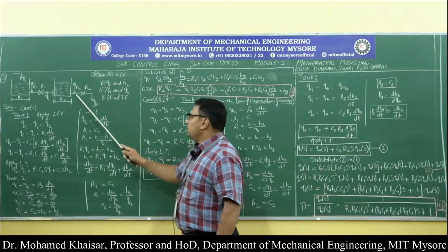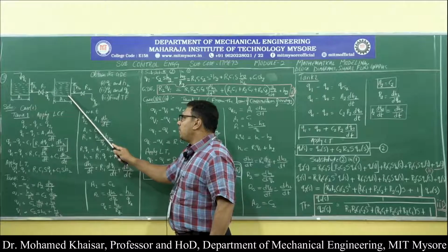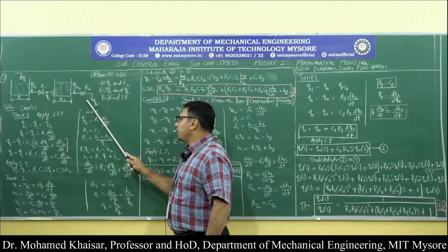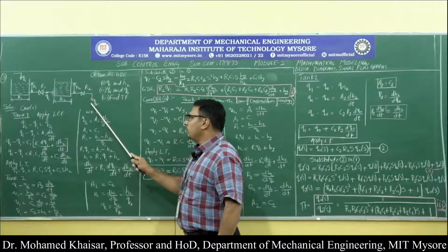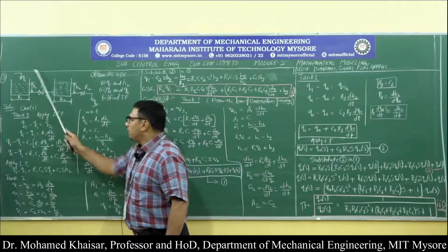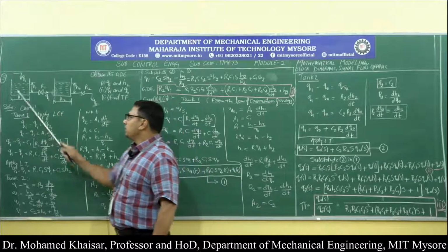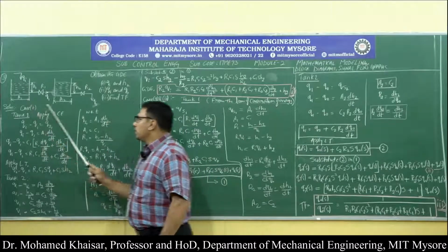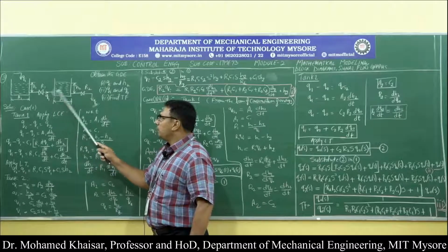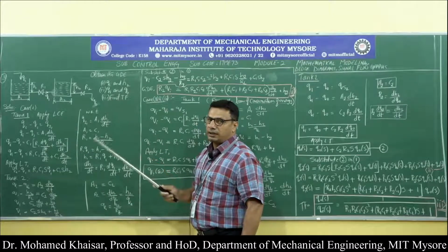Then the liquid that comes out of the control valve of tank 2, after being resisted by the hydraulic resistance R2, the outflow from tank 2, will be equal to Q0. So ultimately, with 2 tanks, if we consider 1 tank at a time, which is the procedure to follow, then Qi is the input to tank 1, Q1 is the output from tank 1, Q1 becomes the input to tank 2, and Q0 becomes the output from tank 2.